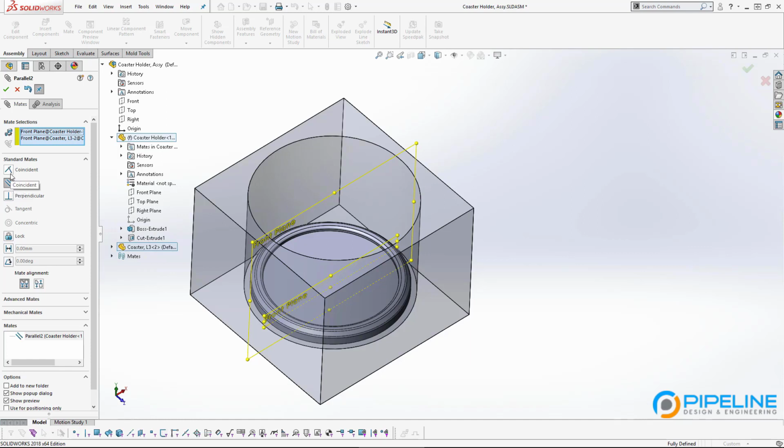I don't have a great way of explaining that, but a coincident mate happens to work, but it doesn't need to be used. So I usually will just make this parallel because who knows, maybe there's a reason why I might offset the circles, or maybe that circle will be offset in the future, and then that actual mate will be broken. I could actually show you an example.